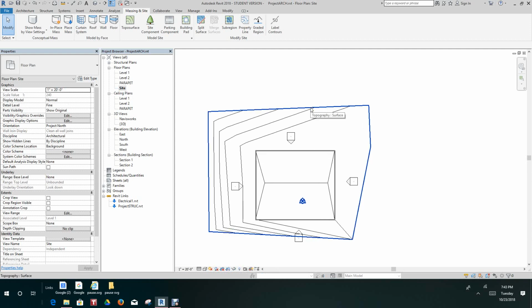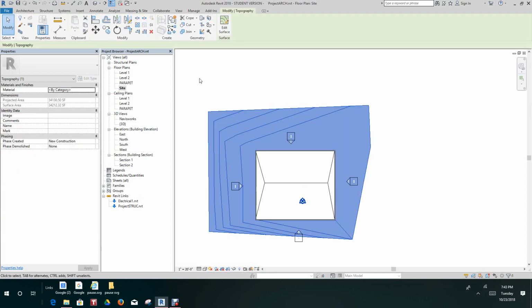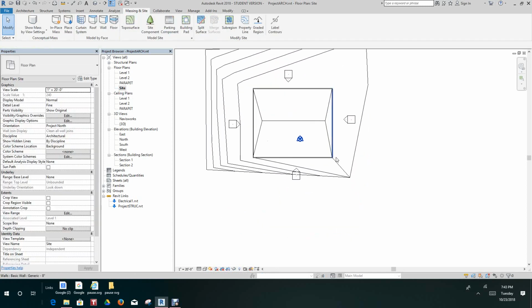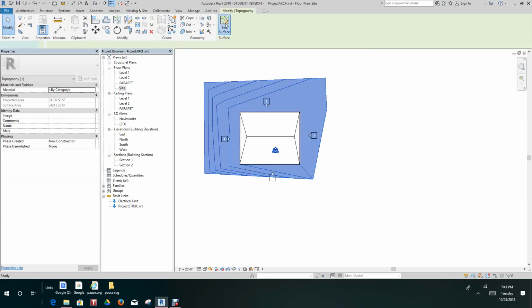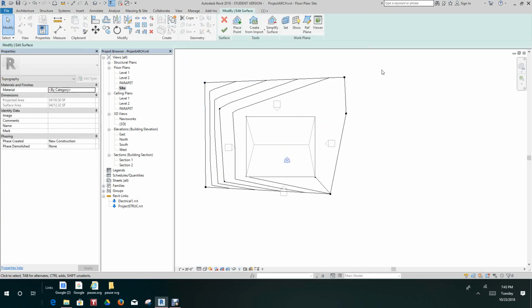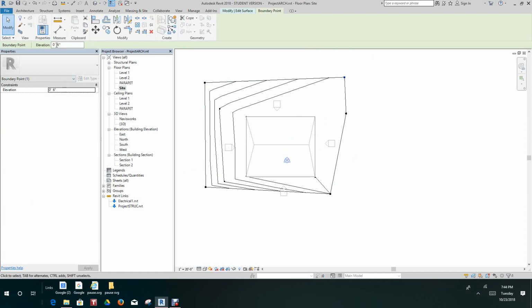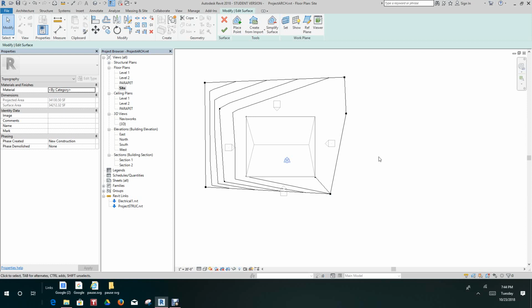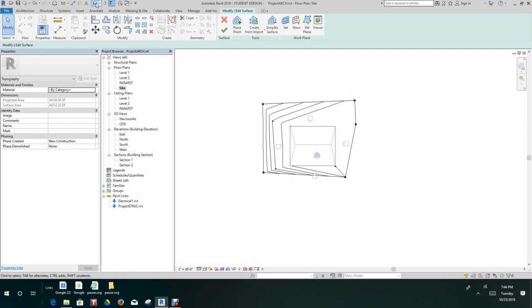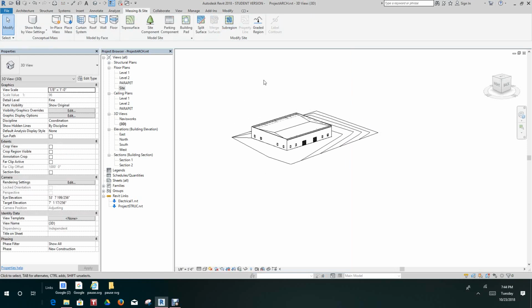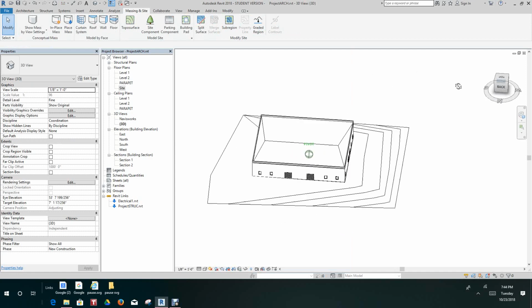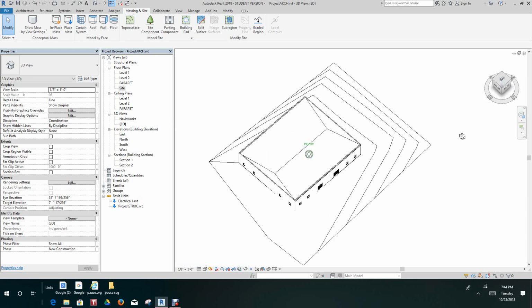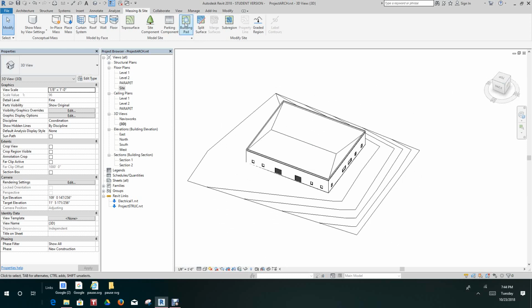Okay. So just remember, if you want to edit this thing, you just select it, edit surface, and then our spot elevation, you can change the heights there. Okay, so that's 6. Now let's finish this. Now next, we'll have our building. So now we need to add a building pad here. This is a modal thing as well. So let's go to building pad.